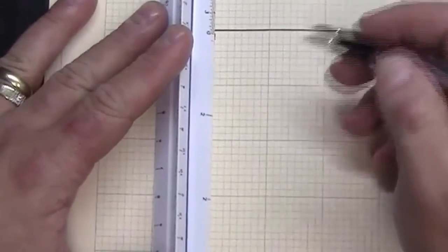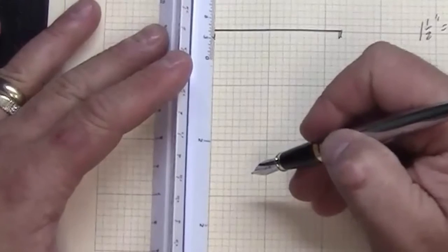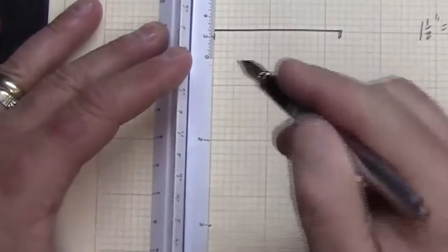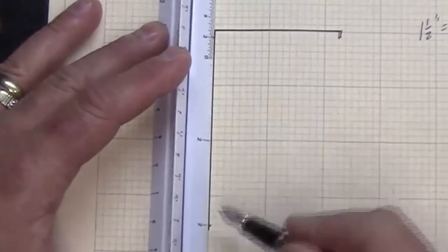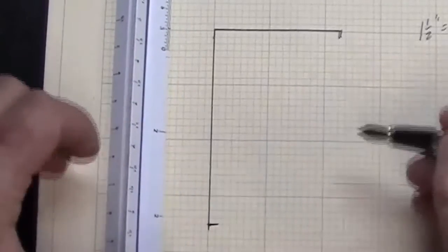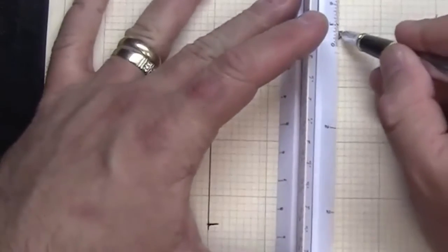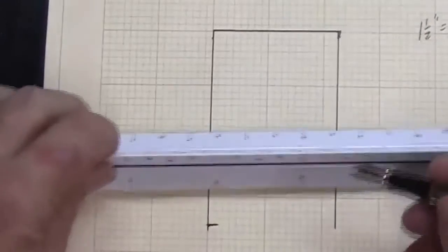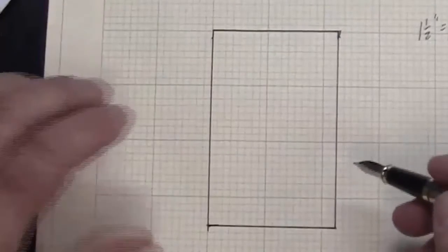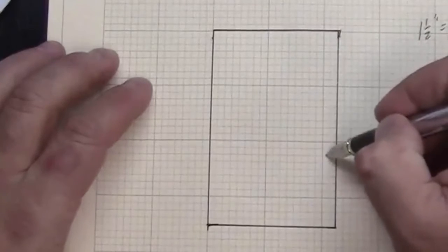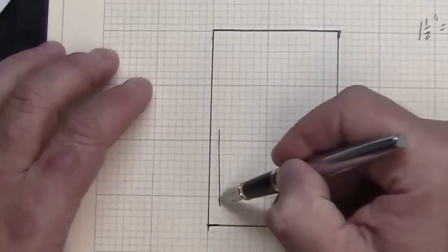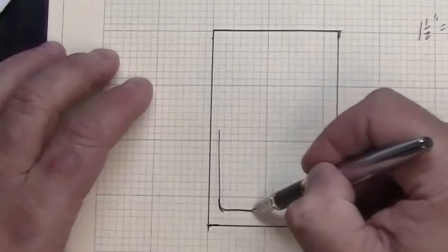I'm going to go down 28 inches. Simply put, that's the major line here plus 4. And I know on the sides I'm going to have 1.5 inch clear cover. I'm going to hold it 2 inches off the bottom.